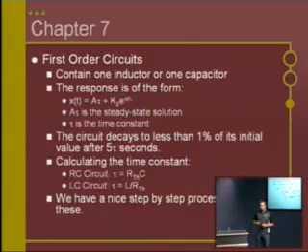And I think what people will continue to do, and what perhaps even occurred on the quiz, was say, okay, well, there was a current source here, the inductor was acting as a current source, and then when we start doing Thevenin resistance and stuff, that's when we pull out the current source and it turns into an open circuit. And I think that was the problem.